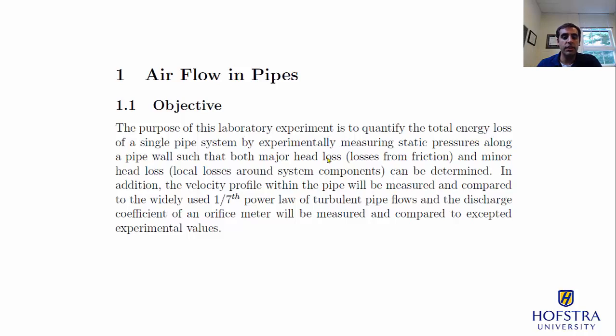In addition to that, we're going to be looking at the velocity profile at the exit plane. We're probably going to see a turbulent flow, so we should see a 1/7 power law. And you might recall if it were laminar, which it probably won't be, you would get a parabolic flow profile. But what I wanted to highlight there is the maximum velocity in the center of the pipe, where it transitions somehow to zero velocity from the no-slip condition at the wall.